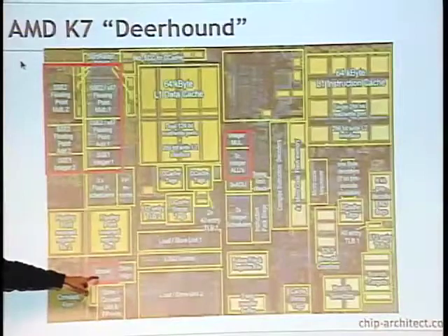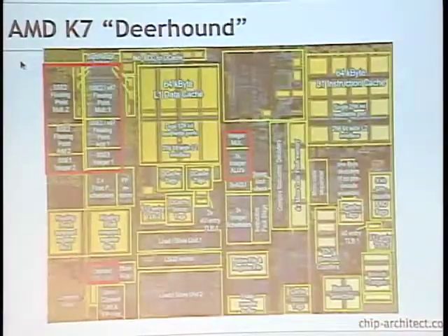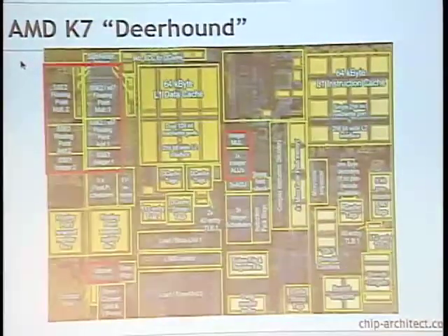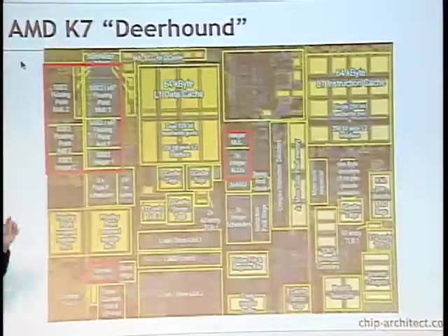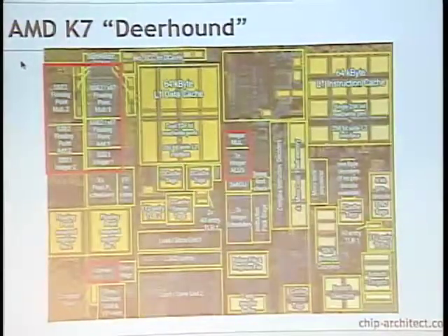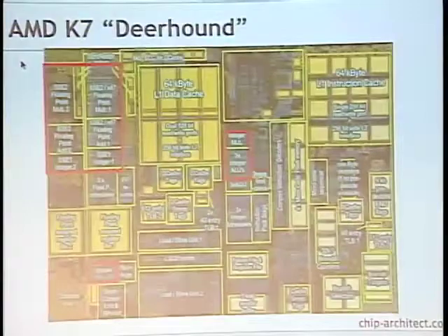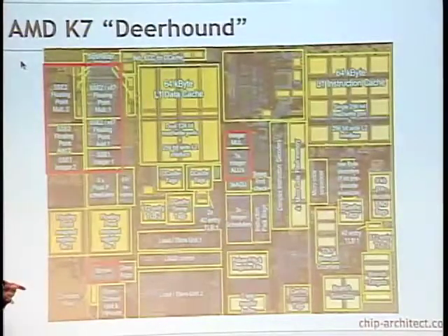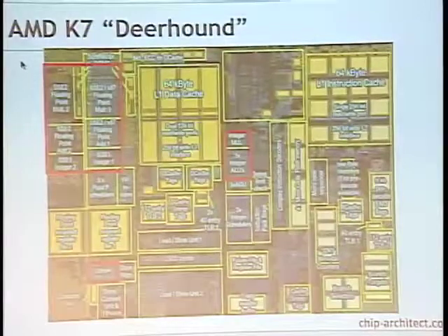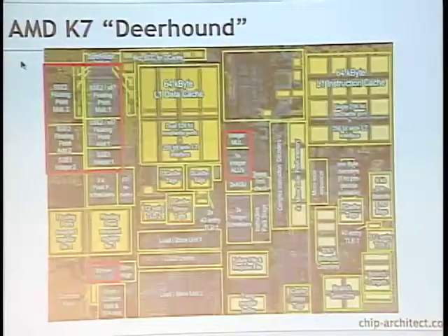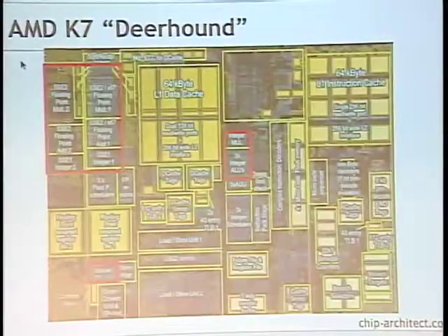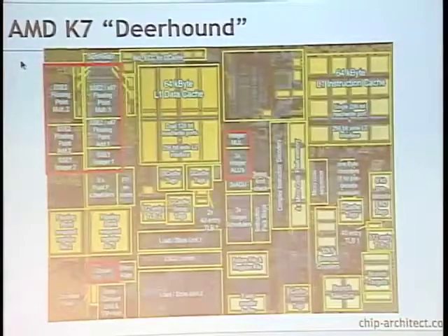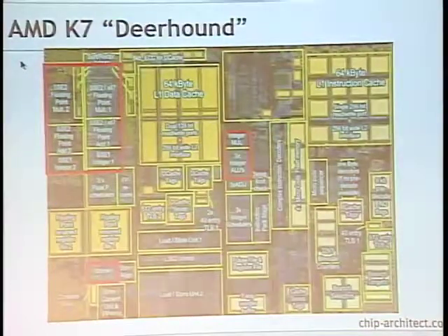This is 3DNow!, which is AMD specific, some graphics extensions. So that lets you do graphics on the CPU. This is all the floating point stuff, and most of that is SSE. So we start to have parallel graphics, 4 things at once. That's where most of your area is going. So there's more data path because they're able to do 4 things at once. But if we look at a GPU, and I wish they'd give us the die, this is something that would hopefully, and I would expect, have a lot more data path on it than what we see here.